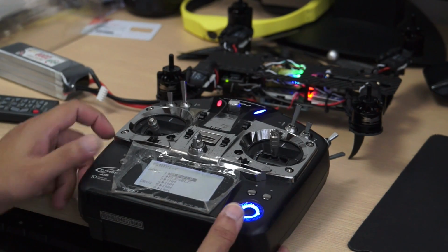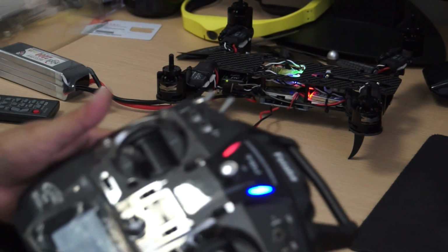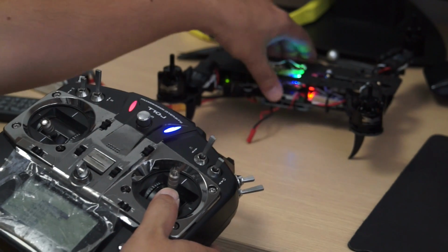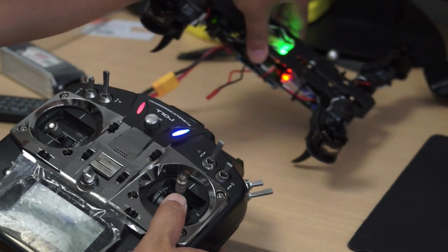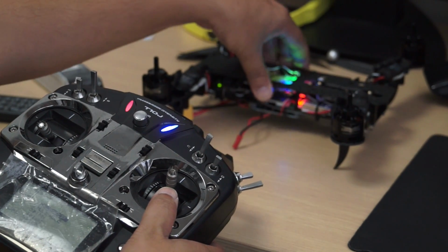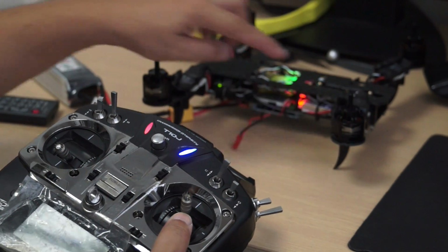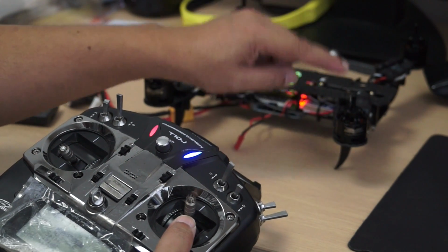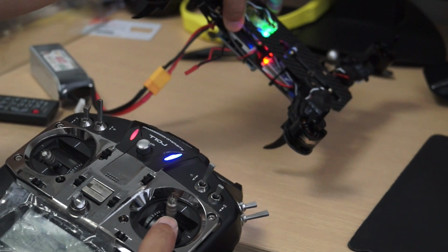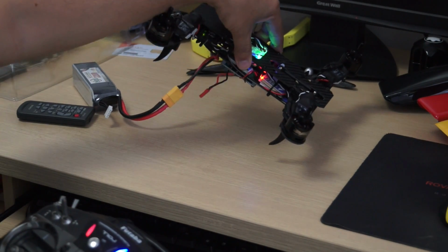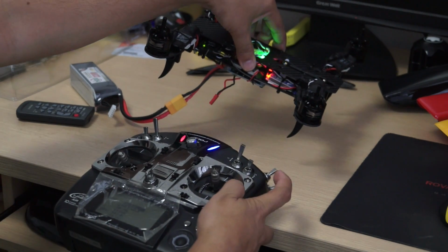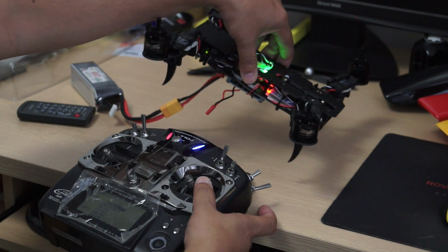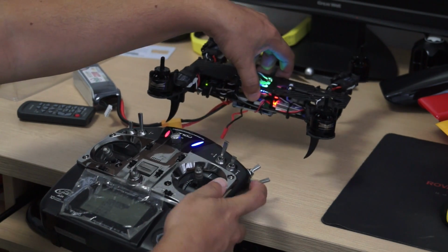Now for the second mix, let me describe a little bit of concept. When you push forward on the stick, that is elevator stick, your quadcopter will tilt and then move forward. You don't want your quadcopter to tilt too much. You want your motors to tilt more and your quadcopter to pick up its speed on the motor tilting rather than the whole quadcopter tilting. Because if the whole quadcopter tilts and your motors are also tilting, your quadcopter will dive down and it will be difficult to control. You will pull back on motors and the quadcopter will climb up. So it's difficult to control.